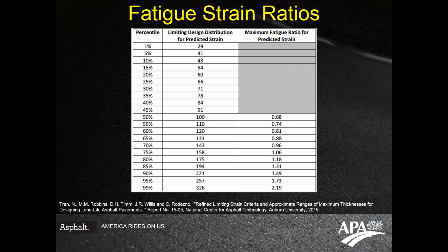If you're designing a perpetual pavement, you want to be at or below, in terms of strain levels, those percentiles. One of the other things that came out of the work was to recognize that not every mix that we want to analyze or use in the field is exactly like we have at the test track. So through work that Dr. Willis did, and then later Dr. Tran's work at NCAT,